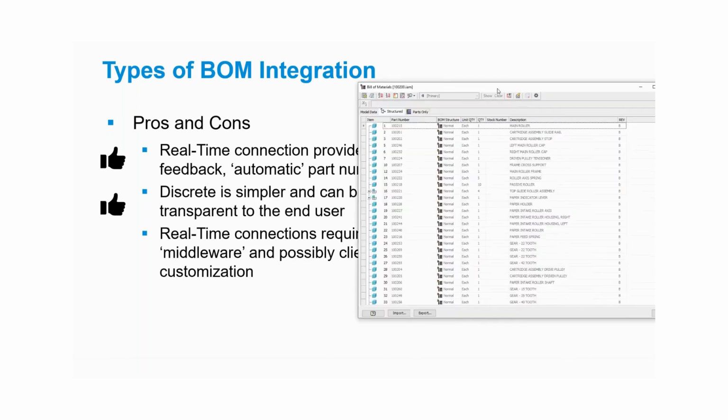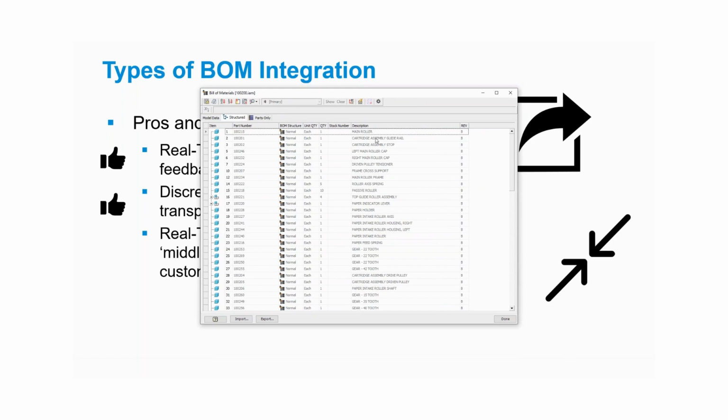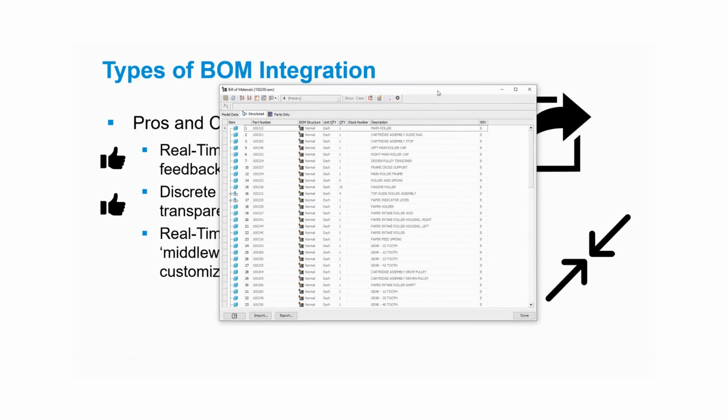So again, if we look at an Inventor bill of materials window, there's nothing built into this dialog that would say, okay, connect to my ERP system and show me the BOM in ERP so I can compare. So you usually have some sort of client-side add-in, like the add-in for Inventor or add-in for Vault that lets you do those sort of comparisons and lookups, right?